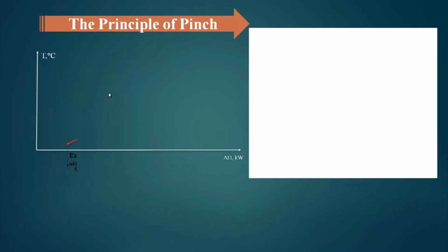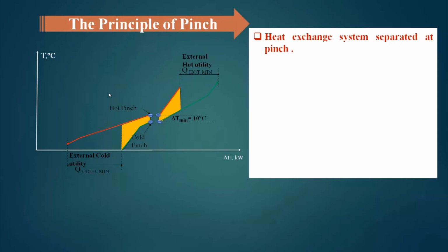Now, we will derive some principles of pinch. In the pinch, we have seen that no heat transfer takes place, and hence the pinch point divides the problem into two parts, and thus I can separate the complete problem into two parts from the point of pinch.